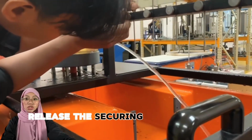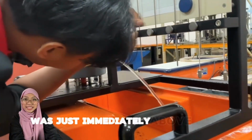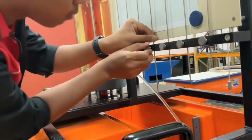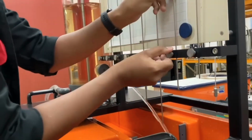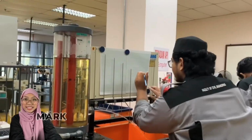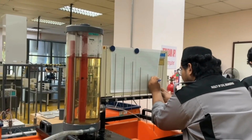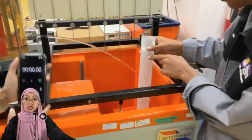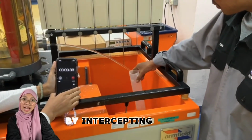Release the securing screw for each needle and move the needle until its point was just immediately above the jet, then retighten the screw. Mark the location of the top of each needle on the graph paper. Using the measuring cylinder and a stopwatch, determine the volumetric flow rate through the orifice by intercepting the jet.